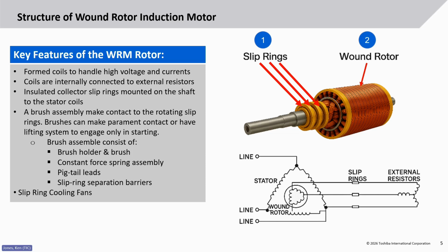And that rotor assembly, when you look at it, has the barriers between each phase, as well as the unique slip ring designs, which are typically bronze or copper with regards to their design. They're not like a synchronous motor in its configuration, where you're looking at minimal voltages and currents, but are designed for more robust configuration and operation.